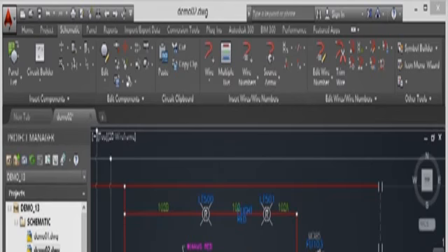One of the lovely features when you're editing components in an AutoCAD electrical drawing is you can select the component, right-click on the component, and you get a fantastic right-hand shortcut menu. Now, on most of the components, the scoot option is there, so I can click on Scoot again, take it back along the wire to this end, and it scoots it back again. Now, the nice thing is, even though I've just scooted that to the right-hand end of the wire, I can click on it again and just keep going until I press Escape or Enter. So let's take that back to the left-hand end where we wanted it to be, press Enter to confirm, and there we go.